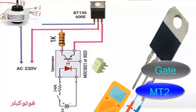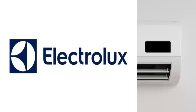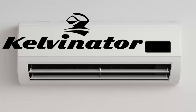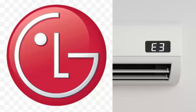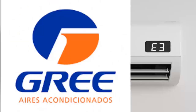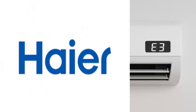Second meaning of code E3. Low refrigerant or very low system pressure. This diagnosis applies to brands like Electrolux, Sharp, Kelvinator, LG, Trane, Gree, Argo, Hi.